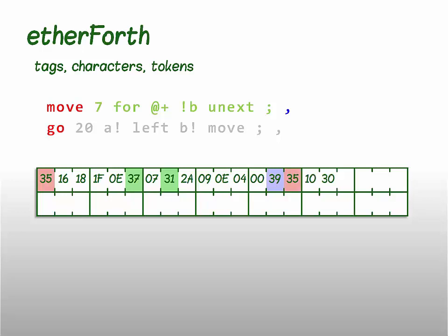We move to the next source line on the display, but we simply continue filling the display buffer, now with a red word Go. We add a hexadecimal number 20, and 3 tokens follow. Notice that word left is not an F18 instruction, but it is convenient to have it as a token too, so it occupies only one 6-bit character in the buffer.